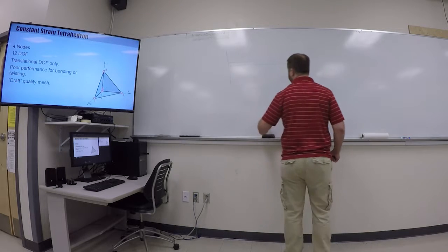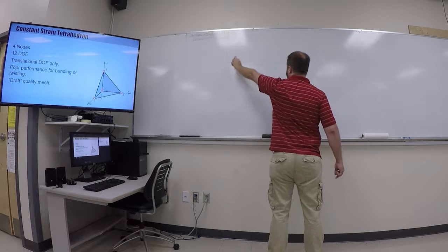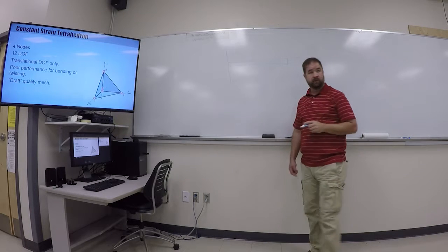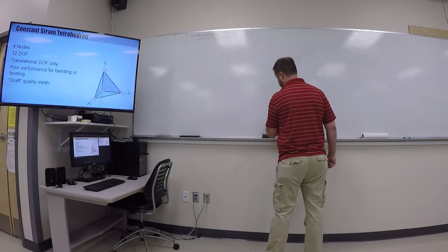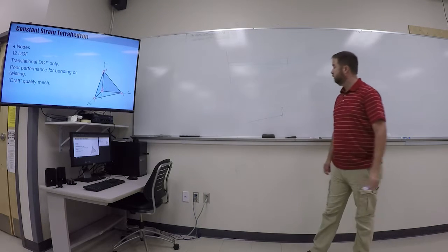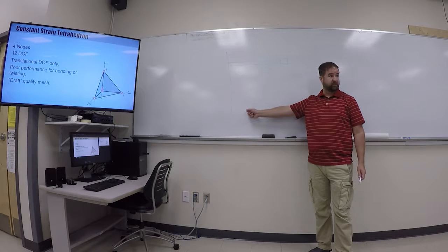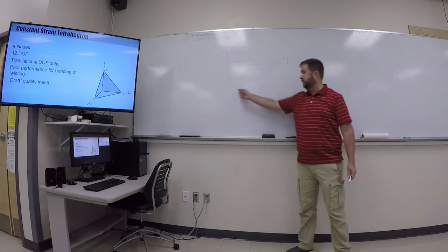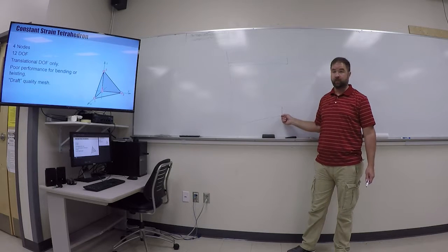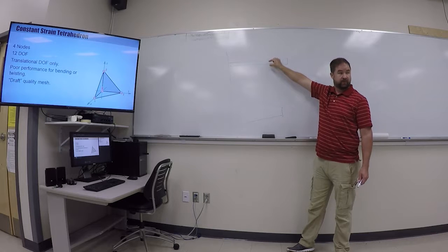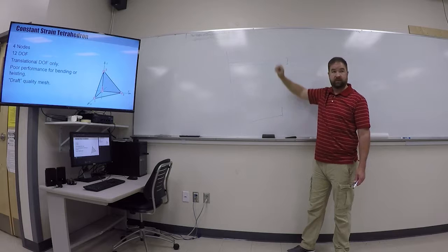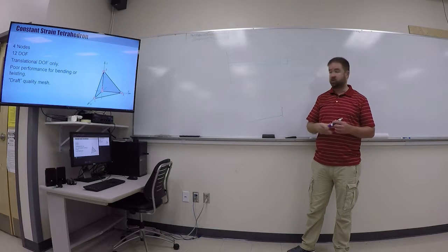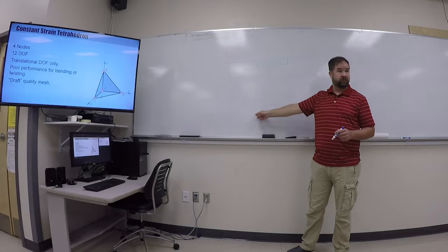If my tapered beam is constant thickness, and in a top view it is tapered, then this is a really good candidate for a two-dimensional element type, because I can capture the taper with my two-dimensional element, but my thickness is constant. And so I don't really need to model that third dimension. So shell elements would be ideal for this.